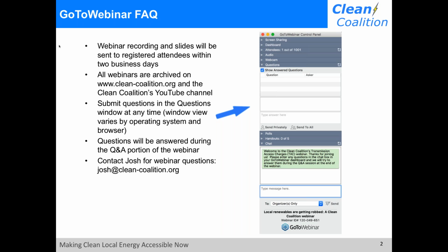Moving beyond that, using distributed energy resource management systems or DERMS, there is a great deal of future potential opportunity to have communication between distributed resources, including aggregate demand response and storage systems, in order to help these work in a coordinated fashion. And one of the long-term goals in hosting capacity assessment is to be able to study and model diverse or non-co-located DER operating on the same grid in a coordinated fashion. But it's going to be a few years until we have, outside of a microgrid context, coordination of DER between each other. Part of the issue there is looking at the cost effectiveness of such systems.